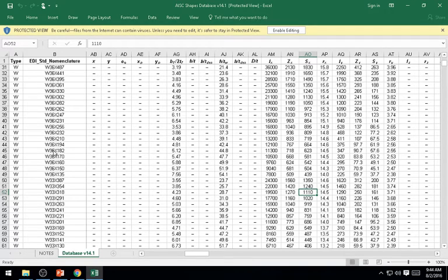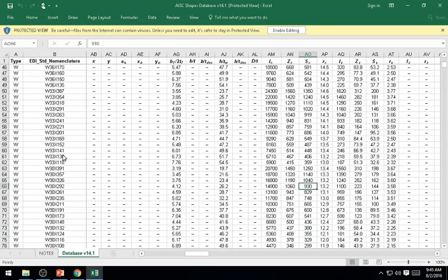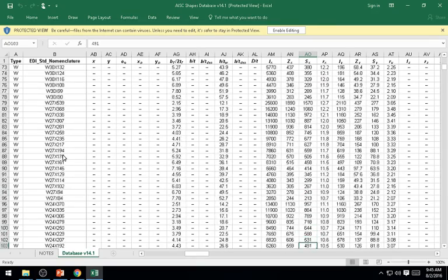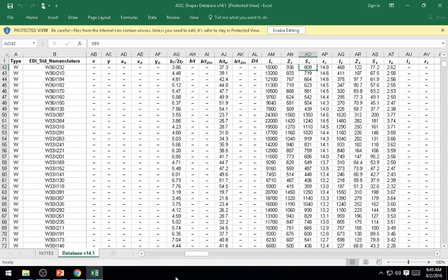So in other words, this is a 36-inch deep beam where each foot of the beam will weigh 182 pounds. And so you would go through here and try to find the lightest section that would have the minimum value of Sx. And that's really how you design.